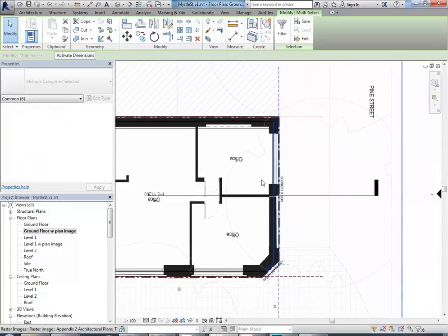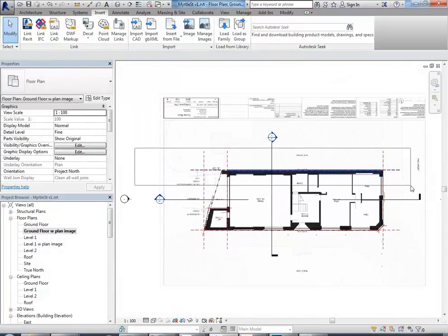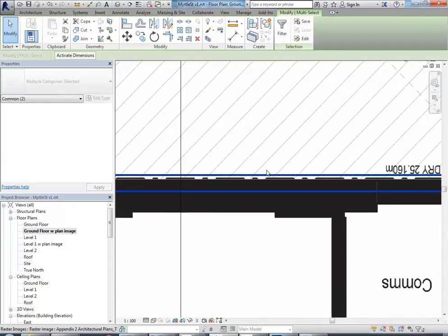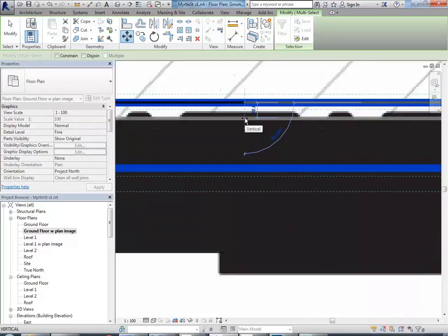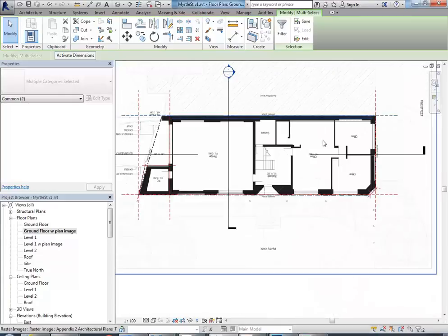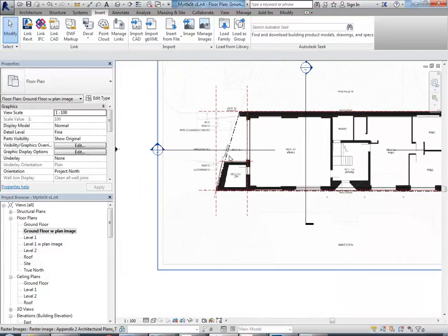So then I can just follow that process all the way around, so the wall at the top here, and by making a window left to right I'm going to get the reference plane as well. And then again using the move tool, starting at the top there and coming down to look at the dimension. Looks like about 60 mil this time. So the numbers are up to you, you just need to make them workable numbers.